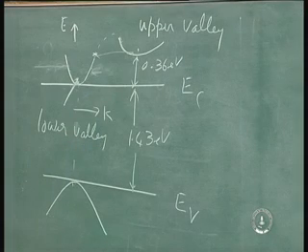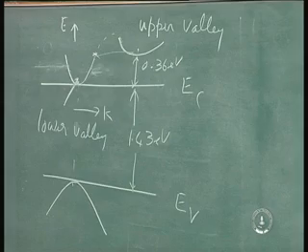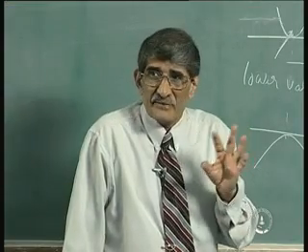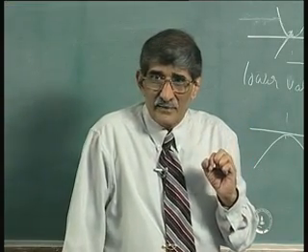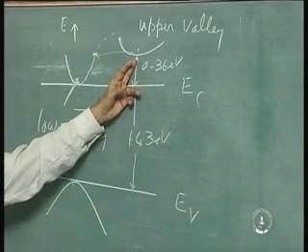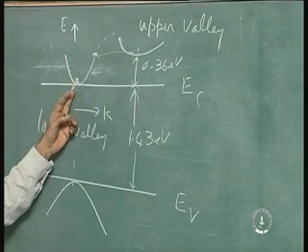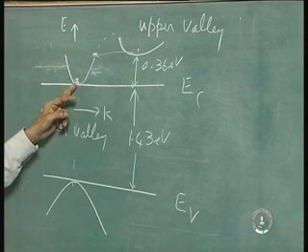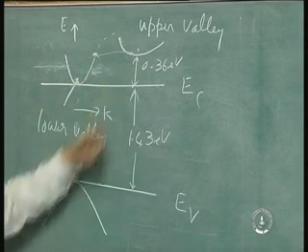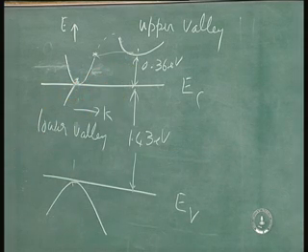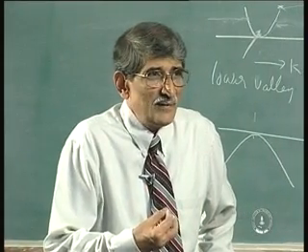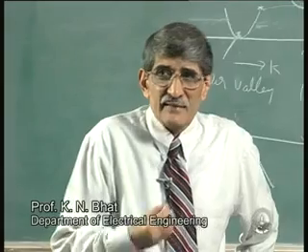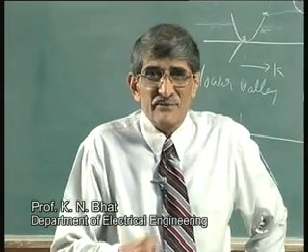Okay. This is a very oversimplified thinking, which sounds quite good from the physical consideration point of view. In terms of energy band diagram, if you want, you can throw further jargons. Electrons get scattered from this valley to that valley. Why do you say scattered? Its mobility falls. Whenever mobility change is there, you say it has scattered. So, inter-valley scattering is called. It is the jargons which are put up.